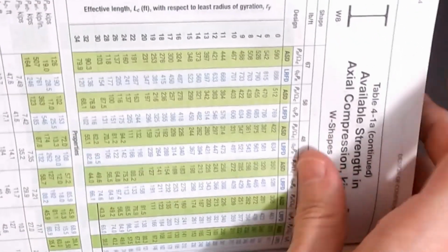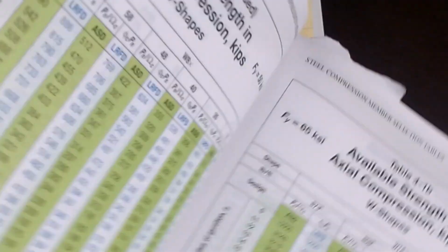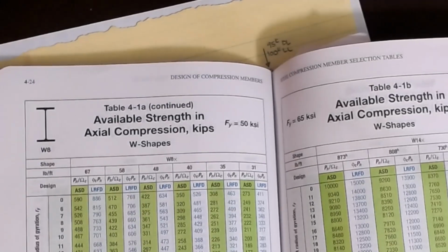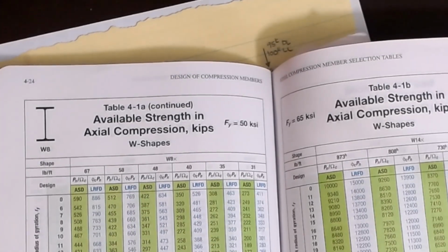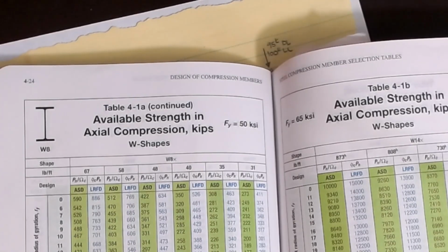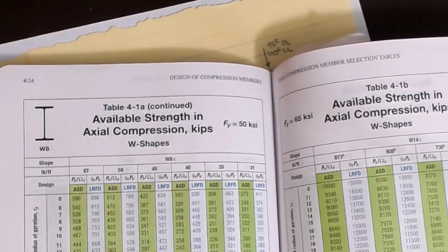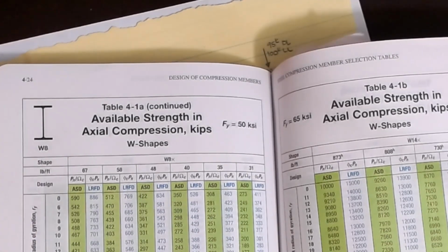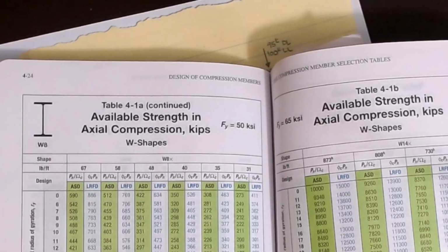As you know, for an I-beam, the Iy value is typically a smaller value than the Ix, which means that the radius of gyration, ry, is smaller than the rx, meaning that it will buckle in the weak direction, as we talked about, strong axis, weak axis, in previous videos. So this weak axis buckling, the Iy, typically is what controls.